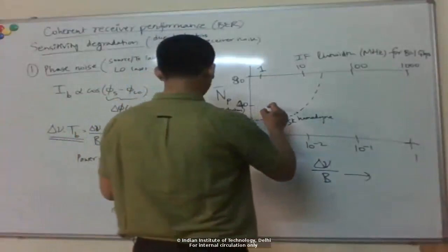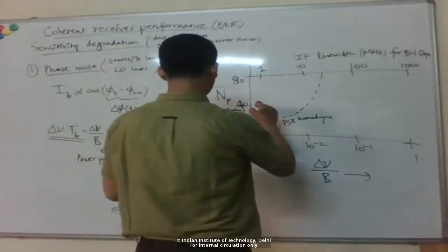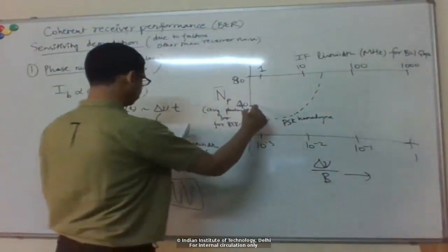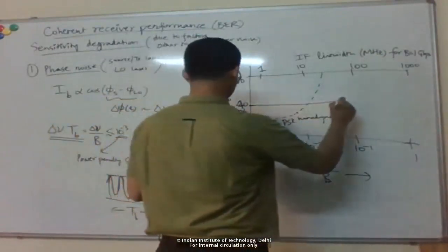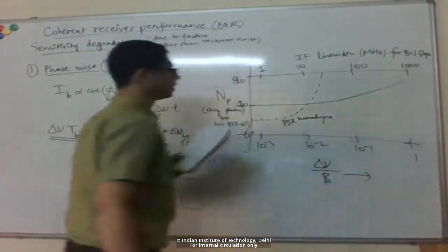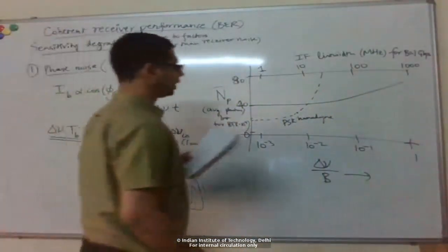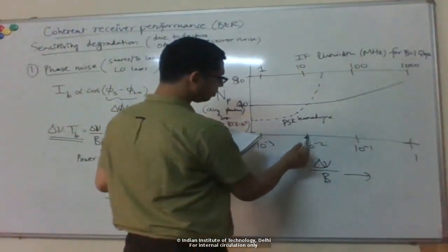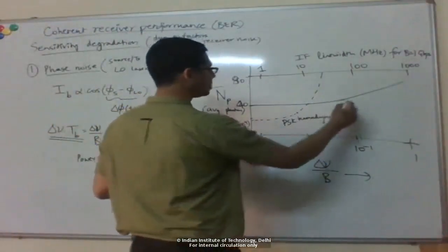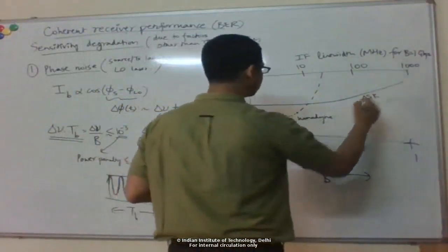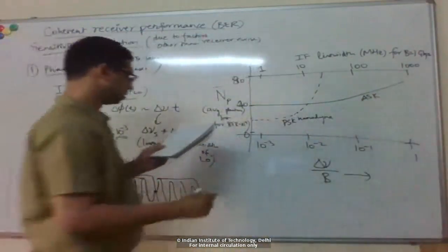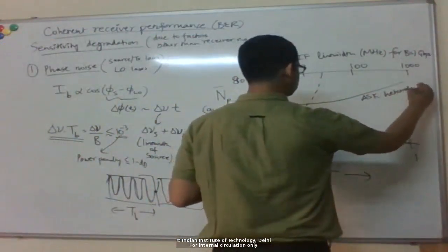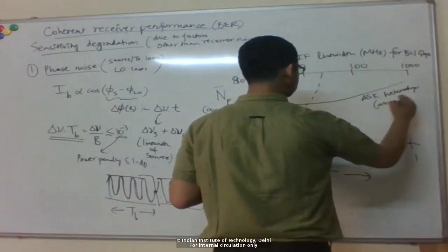Whereas if you look at the other modulation schemes, so for example, if I look at ASK, it of course starts higher than the PSK, right? But it scales much slower, like that. Okay, so you can see that roughly once you go to a line width of more than 1% of my bit rate, then actually ASK becomes better than PSK. So this is ASK heterodyne asynchronous.